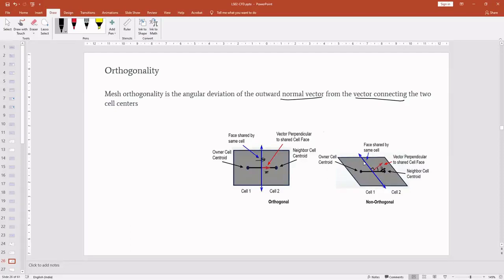If you see, this element is a skewed element. The results can distort if the value of this non-orthogonal angle goes beyond 70. So 65 to 70 is somewhat a workable range. Beyond that, we will consider it as highly non-orthogonal. So in such cases, our computational process becomes complicated, and errors can also creep into the computation.